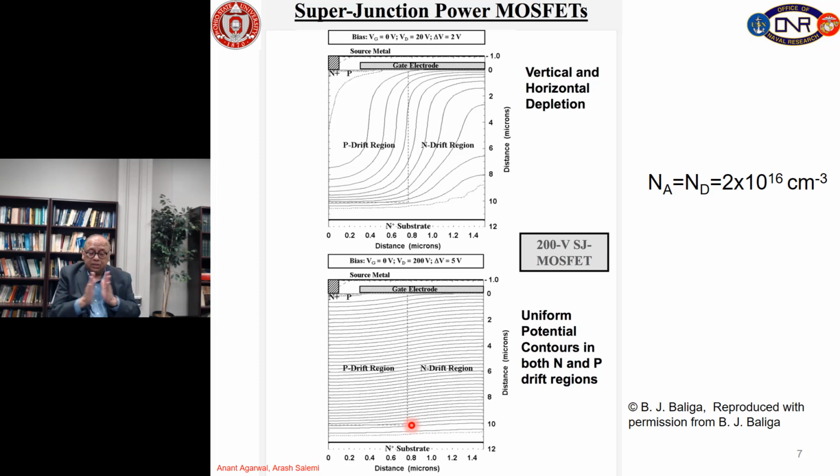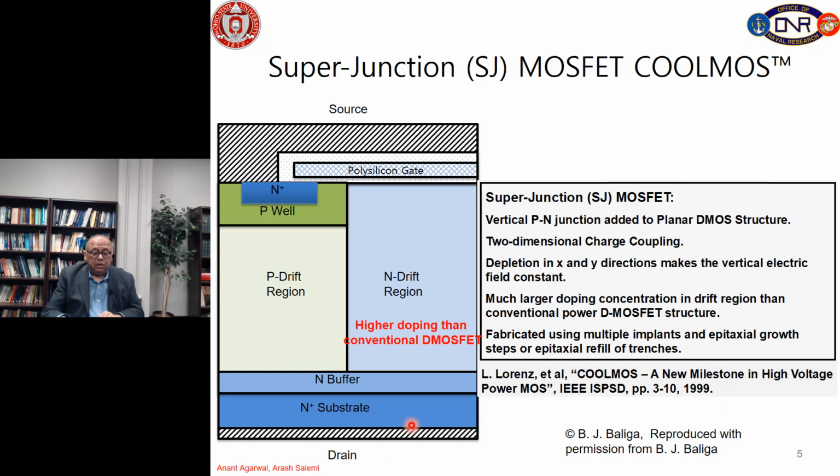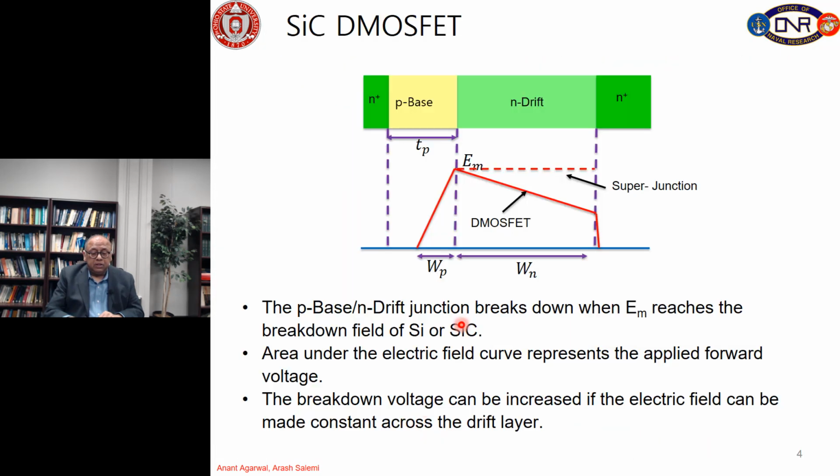So, in X direction we fully depleted at small drain voltages, and then in Y direction we have a high electric field that drops a lot of blocking voltage. So, basically we have been able to essentially get something similar to this constant electric field in the Y direction which we had suggested.